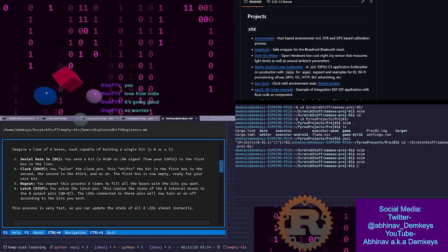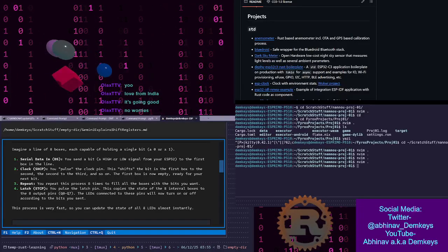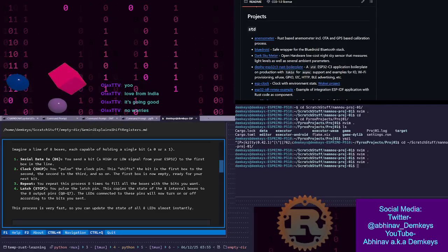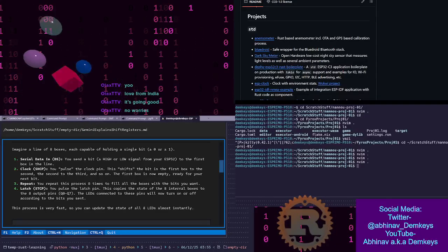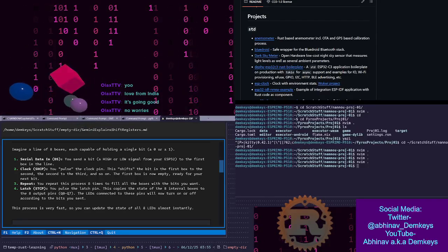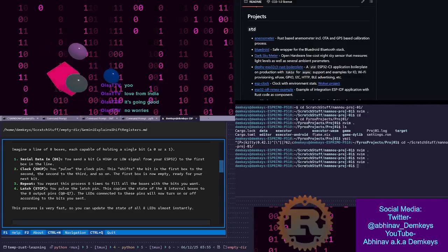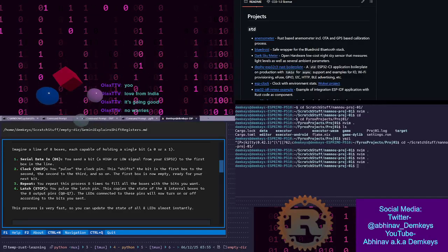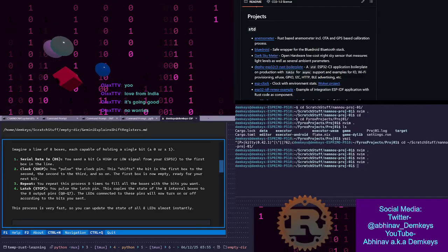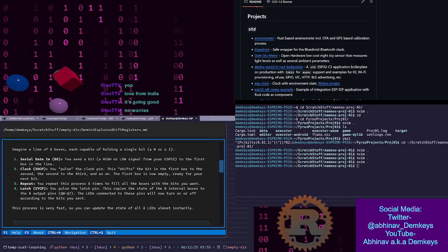Okay, I was assuming that it's going to split the data across these 8 pins, but well, technically it's still splitting, but I think my understanding of how it's splitting was wrong. It's sending it to one pin and then to another, then to another, then to another. Okay, latch. You pulse the latch pin. I'm sure there's some protocol or some library that's already made that handles this communication for you, but it's good to understand how the thing is working.